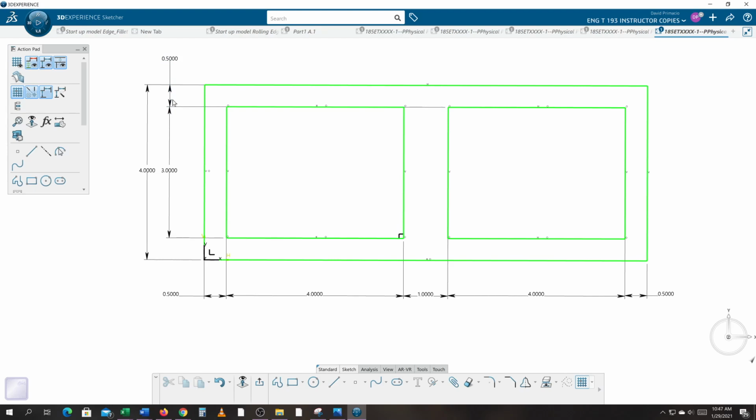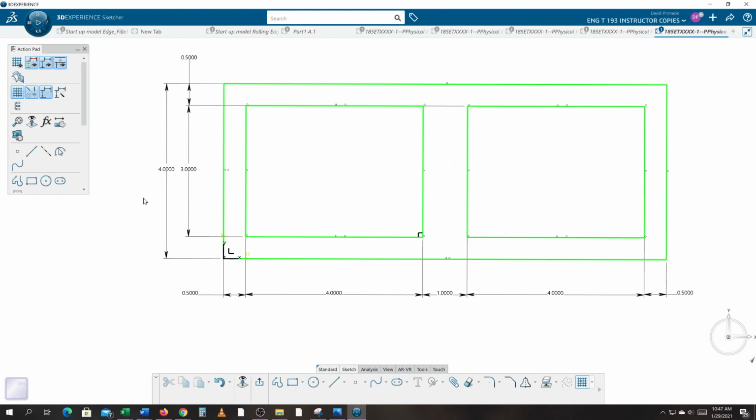Now, I would leave this here for this sketch. We're fine with that, but in the drawing, you want to dimension from the datum to here. I'm presuming that's my datum because I located it on this axis here. So this would be not off the datum here. So why would you create a dimension not off the datum? We told the machine shop or whoever, dimension everything off of this line and dimension everything off of this line, and then we go and dimension off of this. So on the drawing, I really would put the dimension from the datum to this edge.